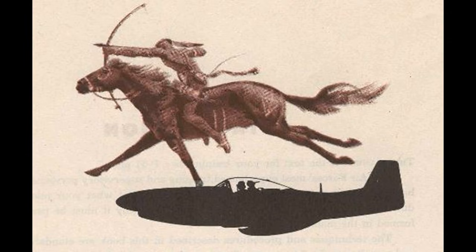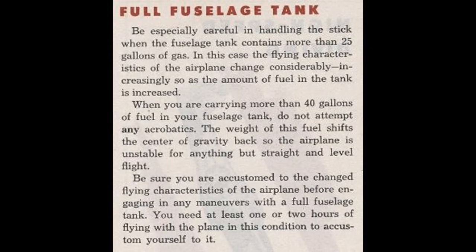One of the ways they got a lot of range out of the plane was to just accept a CG for takeoff with full fuel that was so far aft, the plane would basically fly like crap until fuel from the fuselage tank after the cockpit was burned up. In the P-51, it was critical to burn fuel out of that tank before combat. Of course, due to the distances involved in escort missions, this just wasn't a problem.